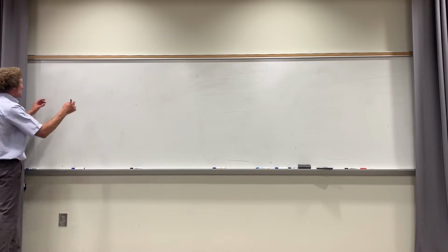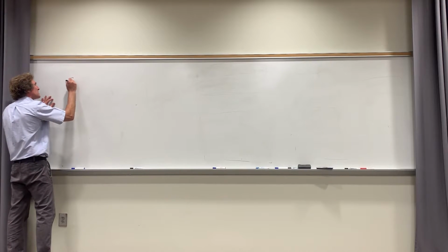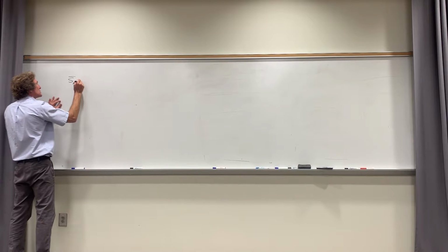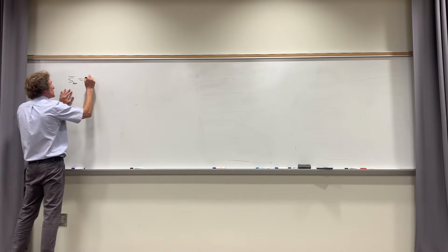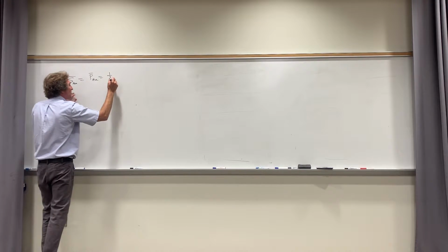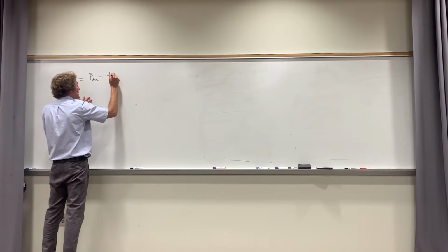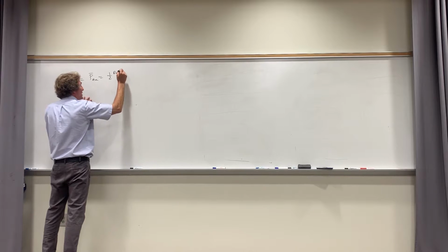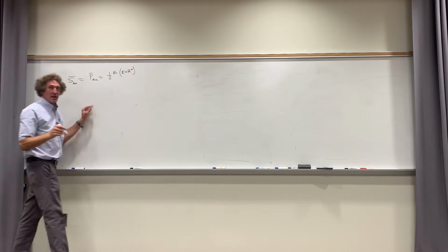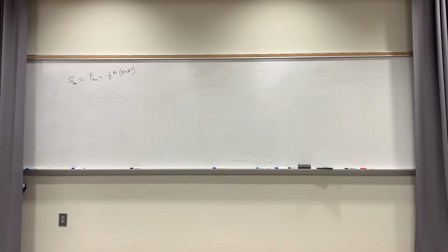This is going to be only when you have an acceleration of charge, which is what we're going to look at. So first, we get the power density. I like the term S because it's more commonly used, and it's the Poynting vector, which is what he calls P_av in his book. And that's equal to 1/2 times the real part of E cross H conjugated, right? Now, I told you before when we were talking about plane waves, does anybody remember if you're in a lossless medium, how we can calculate that? Anybody?